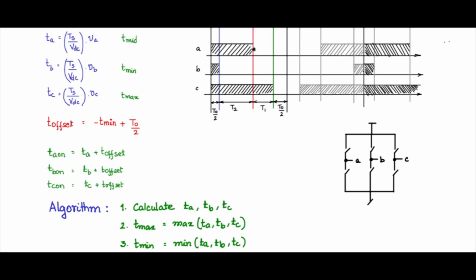So you invert, and when that goes high, you delay it and then make it high, so that the rise time and fall time will pass, and there will not be a direct shoot through period where a huge current can flow. This is what is called dead time inclusion, when in a real circuit you are giving these signals to complementary switches.